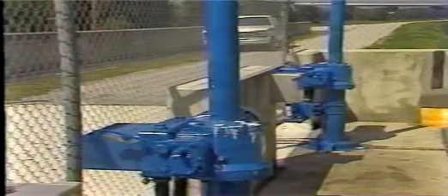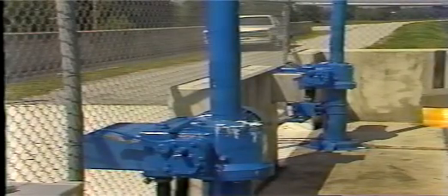Look at the seal plates for evidence of binding, such as scrapes and gouges. Operators should be checked for missing, broken, or loose parts. Look for corrosion damage at hoisting connections and damaged stems or stem guides. Check hydraulic fluid levels and look for signs of oil leakage, especially around the gate stem.